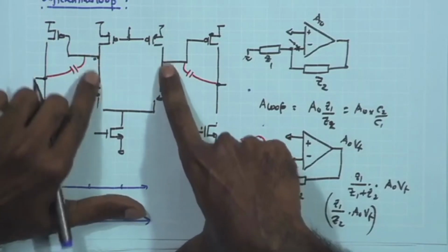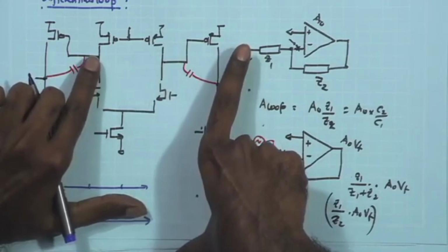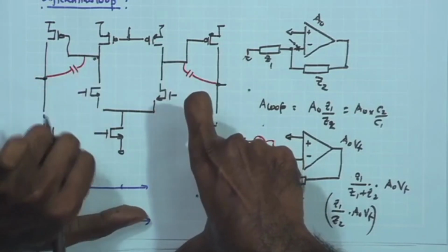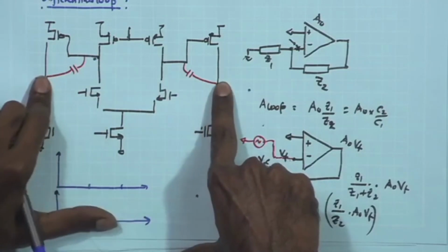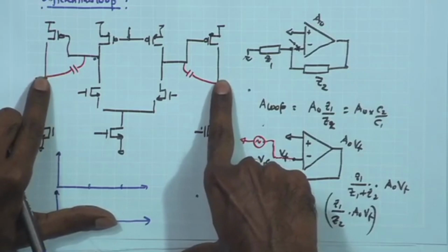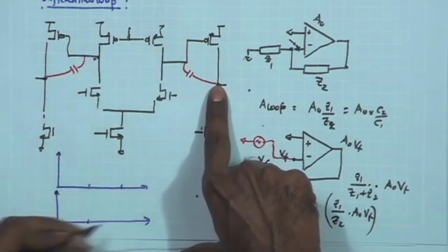We will look into the derivation of the impedances at the cascode node when we look at the cascode or folded cascode amplifiers. So, if you are not clear about that, you can wait for a while. And the final output stage is also having almost the same small signal resistance and capacitance. Therefore, the overall poles at these 2 points will remain almost close.